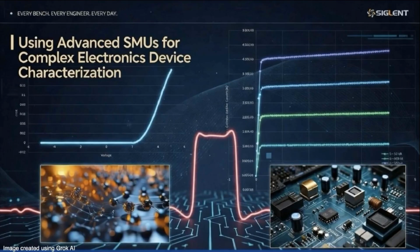Yeah. So I think as you move lower and lower in the current regime, this is where measurements become pretty challenging, right? One of the ways to best optimize it, we talked about some of them. I think environmental and cable interactions are critical aspects. To get below a nanoamp, you really start to have to care about those. You have to care about your cable materials. You start to worry about vibrations. Environmentally, you start to worry about electric and magnetic fields nearby.